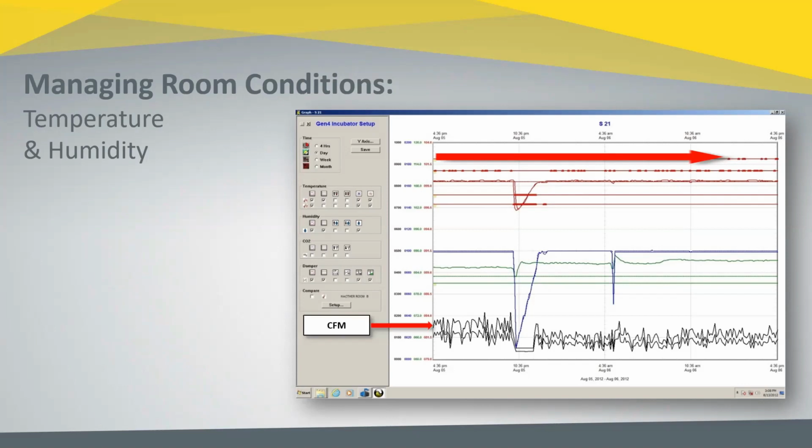We also recognize that air volume through the machine essentially is very consistent, and we see that a damper physically runs more in an open position by design due to the nature of how the machine operates. But with the consistently open damper, consistent CFM, and consistency in temperature and humidity set points, it becomes critical that we control temperature and humidity as consistent as possible in the room.